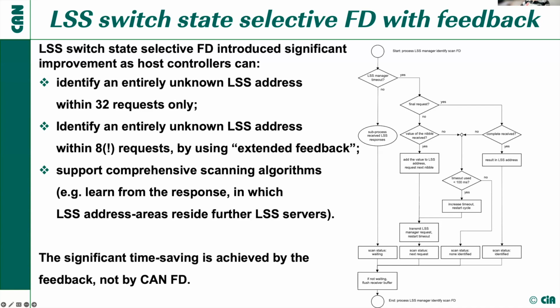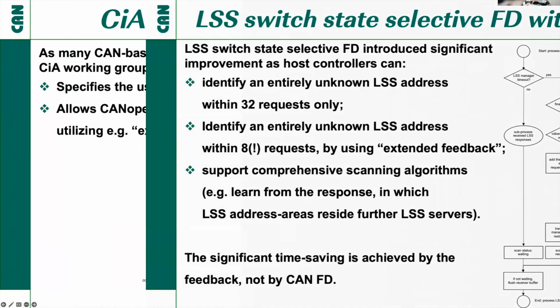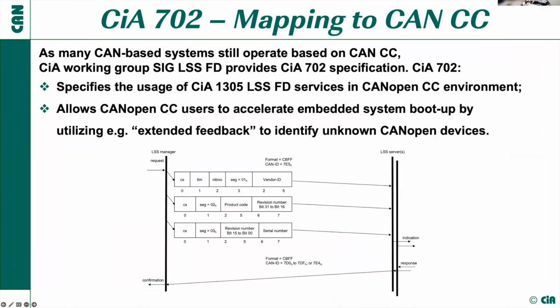Yeah, when we were developing that, then we also reminded us that it is unfortunately the fact that it took a while till CAN FD entered the market and was available in several applications. Therefore, we thought it is wise to offer this functionality also to CAN classic-based systems, so to CANopen Classic systems. And therefore, we provided a document CiA 702 where we mapped this functionality to classic CAN frames.